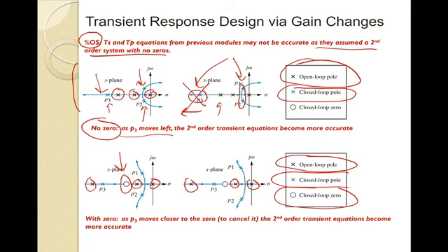And then we are looking at our closed loop poles as we vary the gain. These two poles merge together and then go off axis towards infinite zeros, zeros at infinity. However, looking at this closed loop pole, look what it does. It's migrating towards that zero. So what we're going to see is the following. With a zero added, as P3 moves closer to the zero, what's going to happen? Once they get close to each other, you could imagine a zero here and a pole here.